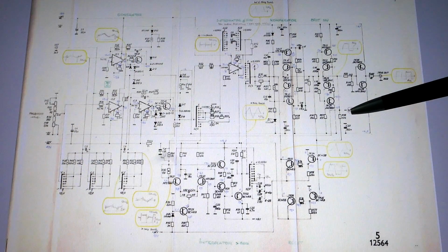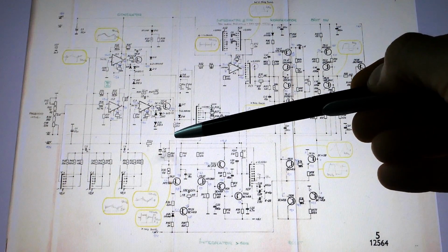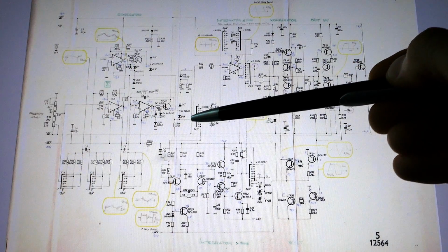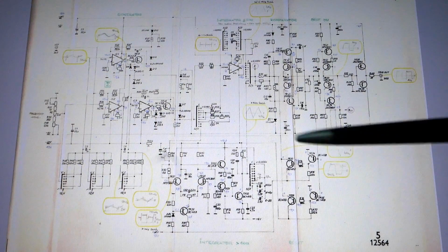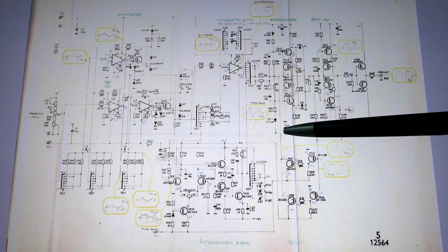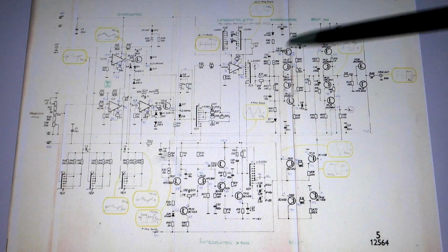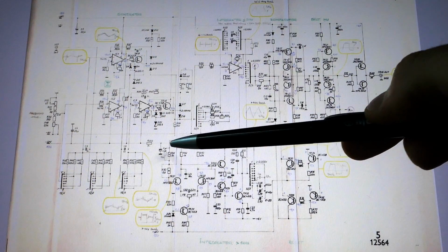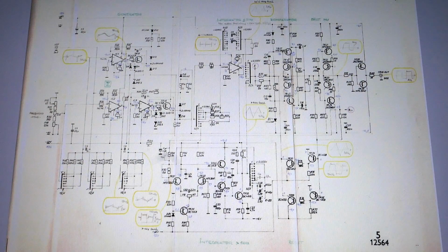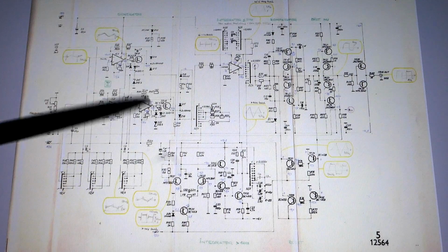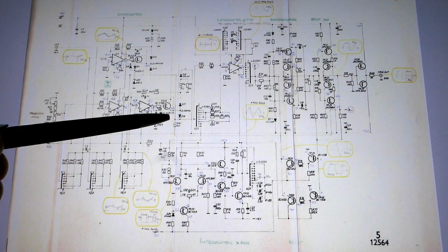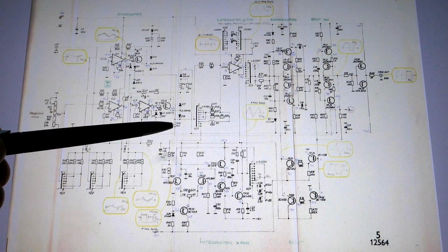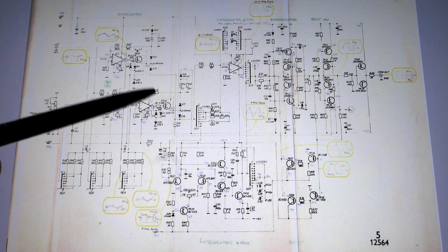The feedback from this square wave from the point B goes via a 510 ohm resistor back into the input of this integrator, or this one. The output of the integrator is basically either rising or falling, and when it hits the target value, this thing flips and also flips the input voltage. So the op-amps are not an oscillator, they are part of some voltage-controlled frequency contraption, and they basically reduce the voltage coming through the feedback. They pull the voltage down after this 510 ohm resistor precisely to some specified level.